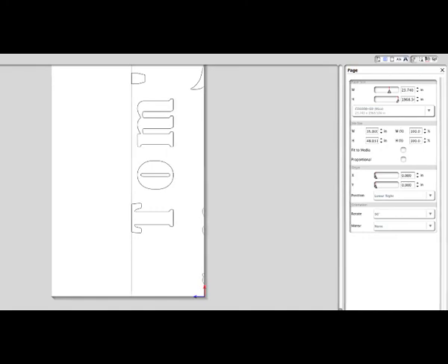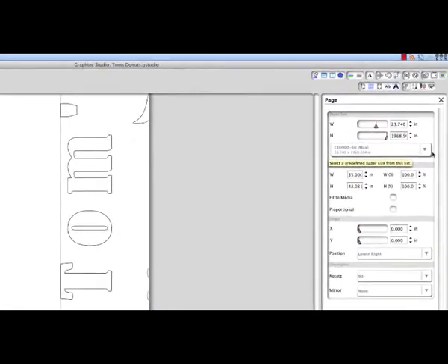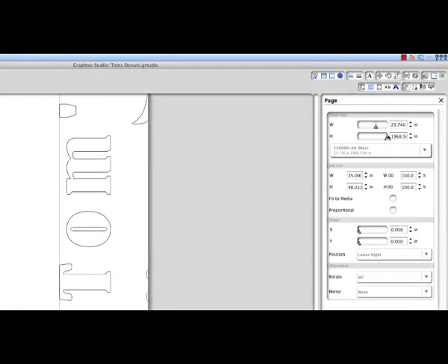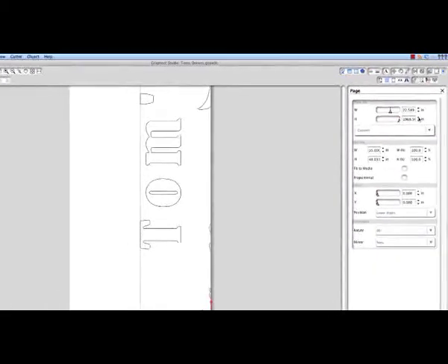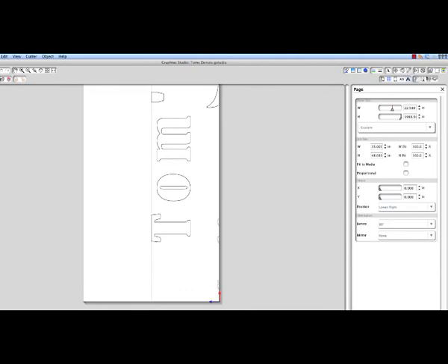The media page size automatically sets to the cut area of the default cutter. The size can be adjusted by using the width and height values in the side panel. The sliders are for sizing the media visually, whereas size values next to the sliders allow for more accurate sizing. Once the width and height have been set, the media page in the cutting preview window will adjust accordingly.